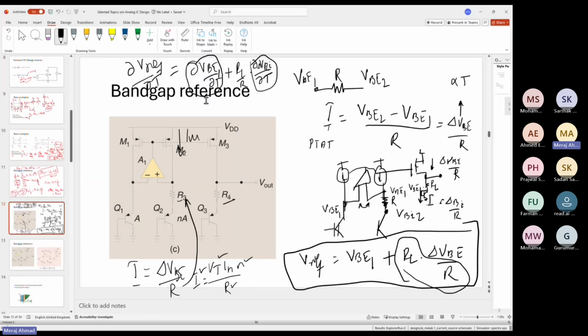So I know that this slope and this slope I'm trying to cancel here, but due to non-ideality, you see the bell shape. This is a flat part. Here you get almost zero temperature coefficient. So you need to consider a bit more design and mismatch non-ideality.